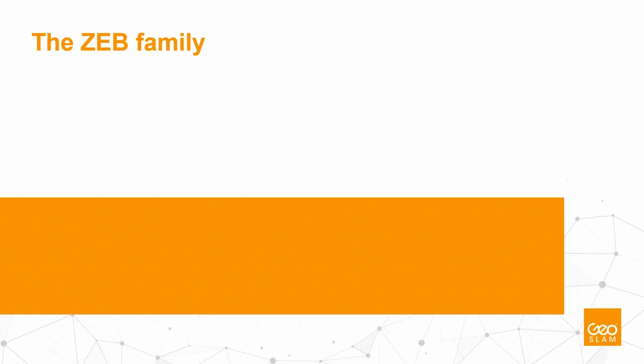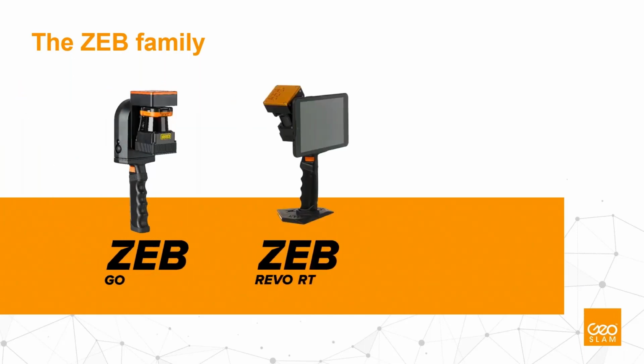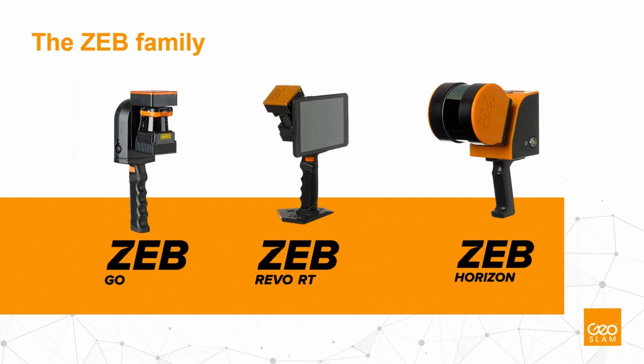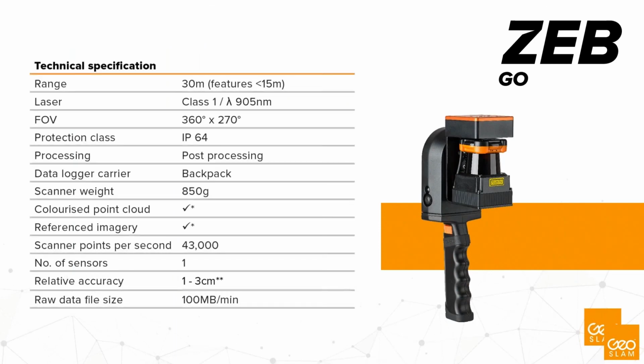Just to quickly go over the actual product family that we have. We have the ZEB Go, the ZEB Revo RT real time, and the ZEB Horizon. So to go over these individually now, our ZEB Go is our entry level scanner, the one that'll probably cost you the least to purchase. We have a 30-meter range on that, IP65 protection class, and a 1 to 3 centimeter relative accuracy. So like that data I showed you, you just simply turn this on, walk around, and you get a point cloud with 1 to 3 centimeter accuracy.